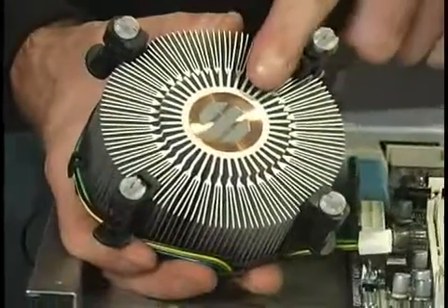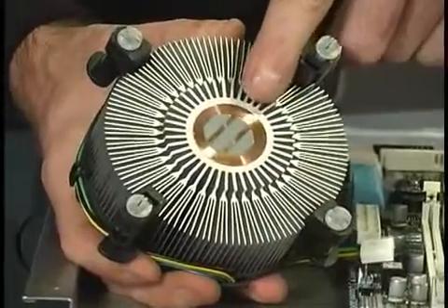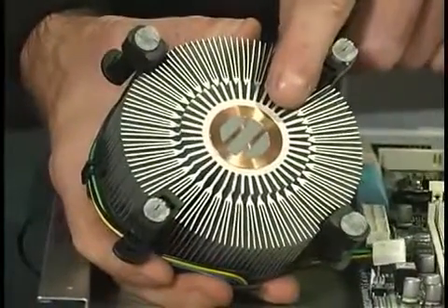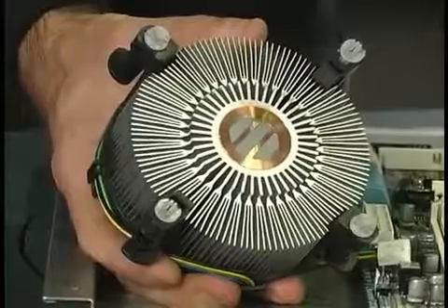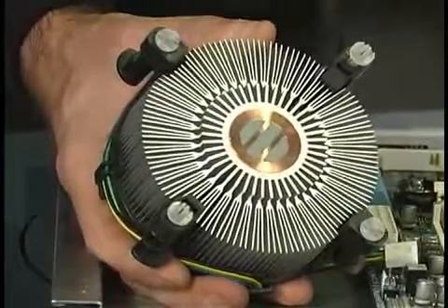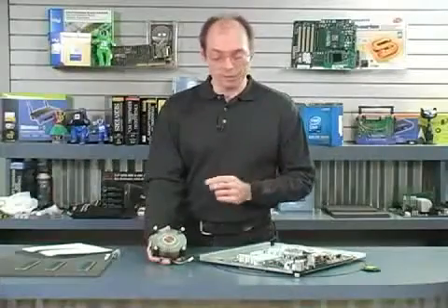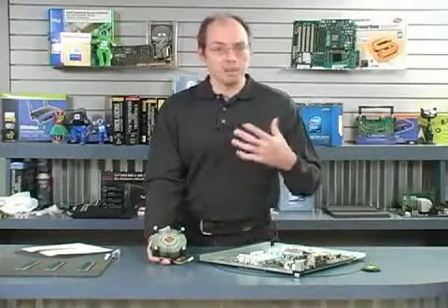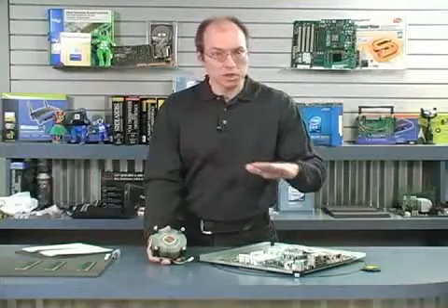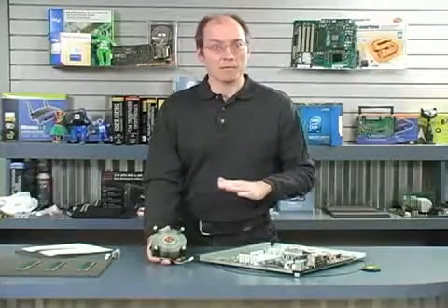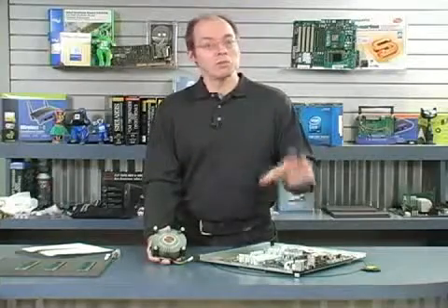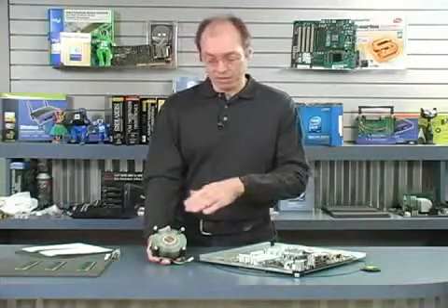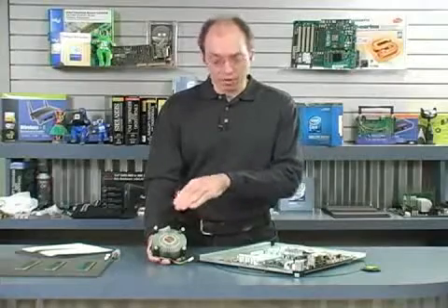As you can see in this example, there are 3 bands of material, and it's a waxy type material. You don't want to touch it. You want to keep it protected until you actually install it, because you can damage it with your finger. Once the processor is first powered up, that stuff will melt, and then it will ooze to where it covers the entire top of the processor. Now, with any thermal interface material, once you remove the heatsink, you have to discard that thermal interface material. It has to be cleaned off.